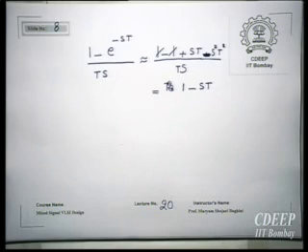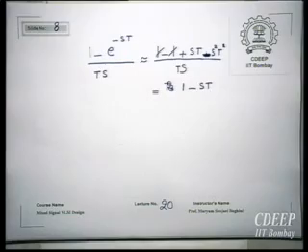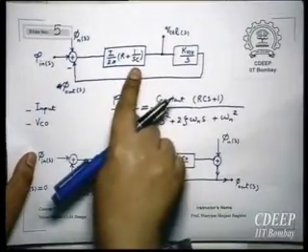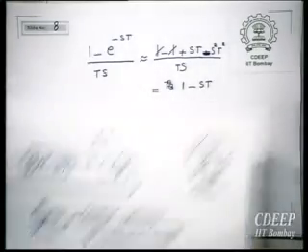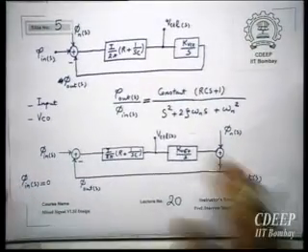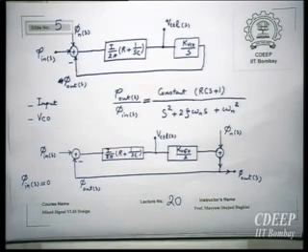This itself adds to the phase, right? This adds some extra negative phase shift, because we had considered everything is continuous time. Therefore, we had just one zero and two poles, right? But effectively, this charge pump is not like this. It has some extra phase shift due to this sampling effect. Therefore, that's why when we design, we have to be careful about choosing the bandwidth of this filter, the phase margin of this filter. So, phase margin should be chosen at a very high value.